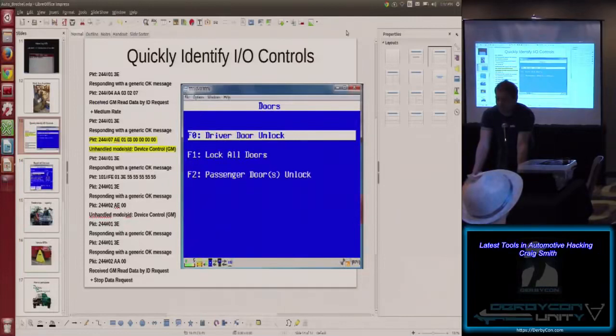While the infotainment unit itself may check the key information, it may not check when it's pushing out to other devices. The other embedded system itself doesn't have an understanding of PKI. So a shortcut that's sometimes used is that the beefier component, the infotainment center, does all the checking, and then says everything looks good and passes it on, usually using just a standard password kind of thing. So you can circumvent the whole PKI by just jumping on the bus and acting like you're an infotainment center, saying everything was cool, it's totally fine, take this firmware.